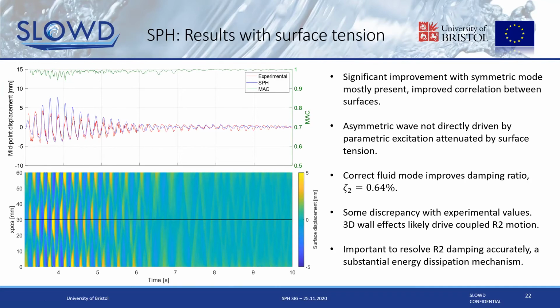We increase our fluid-induced damping here up to 0.64%. But there's still some discrepancy between the numerical fluid-induced damping and what we see experimentally. We're still investigating this, but I think there are three main reasons why. The first one: we're dealing with 2D simulations.